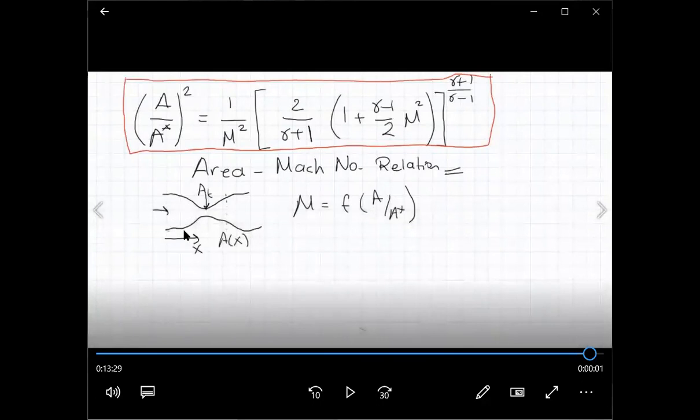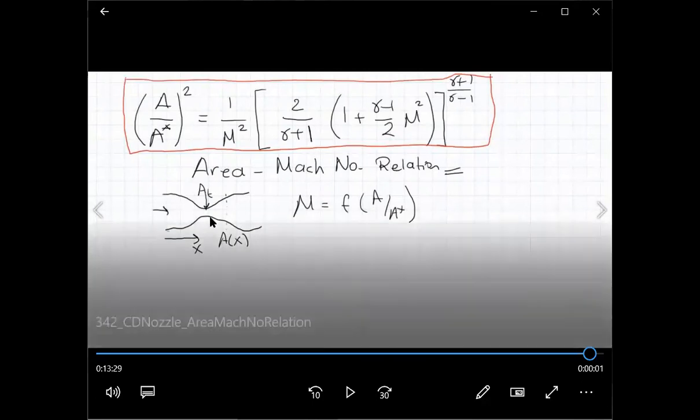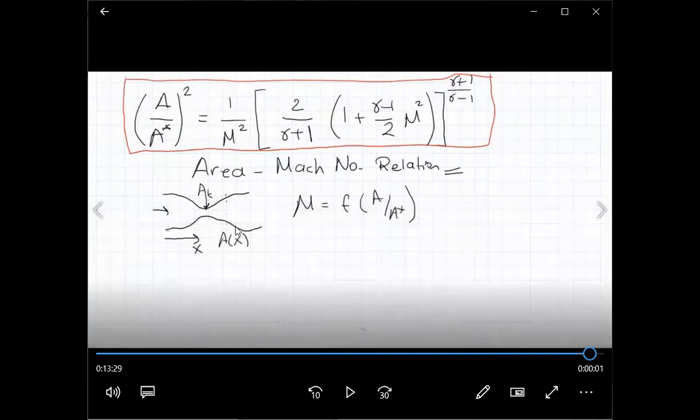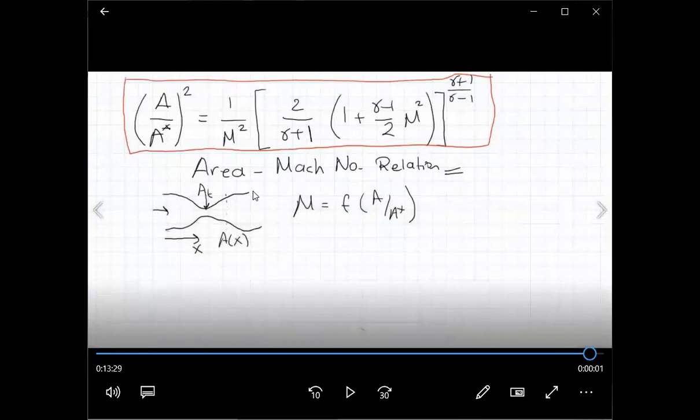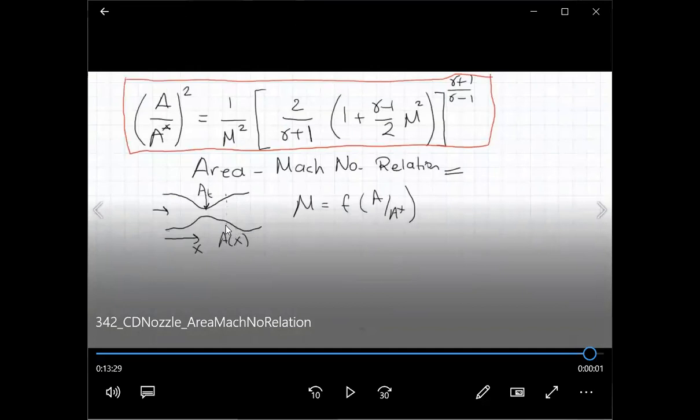So this curved shape is also important, especially in the diverging part. In the converging part, it is not that critical, but in the diverging part, in the right-hand side, the bell-shaped geometry is critical. There are certain supersonic aerodynamics methodologies that we use to design that shape, and that determines the length of the divergent part.